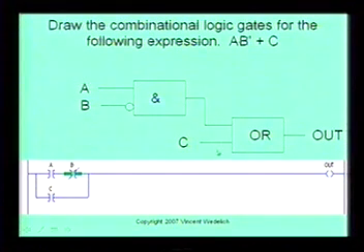And the way you would draw that in ladder logic is simply A is ANDed with not B, ORed with C, gives you your output. So these homework problems shouldn't have been very hard for you. You should have been able to whip right through them fairly quickly.